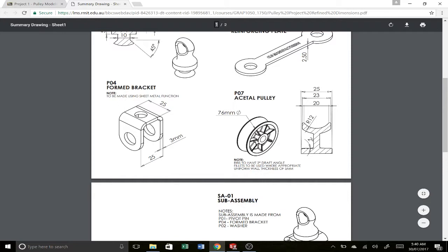And then we are just going to circular pattern all of this stuff and then do a mirror to get it across to the other side. So we'll do one rib, circular pattern it, mirror all that across. So let's begin with this sketch.